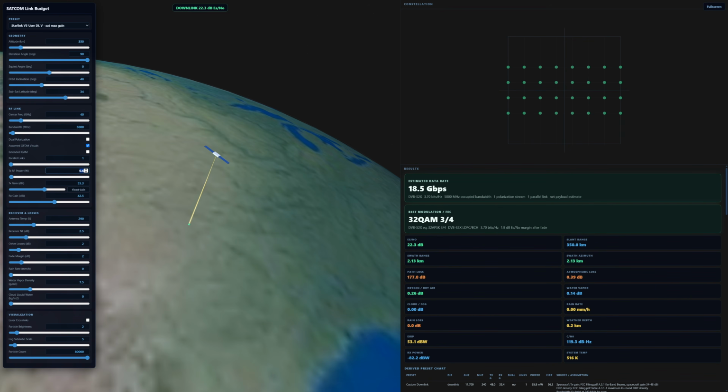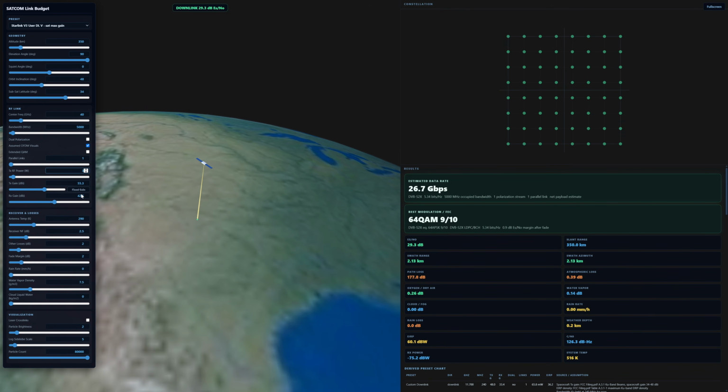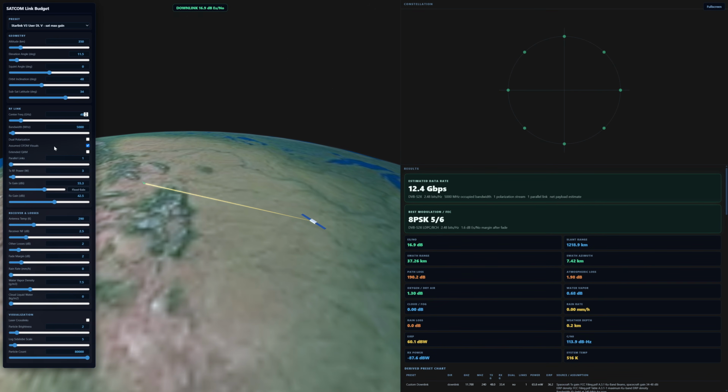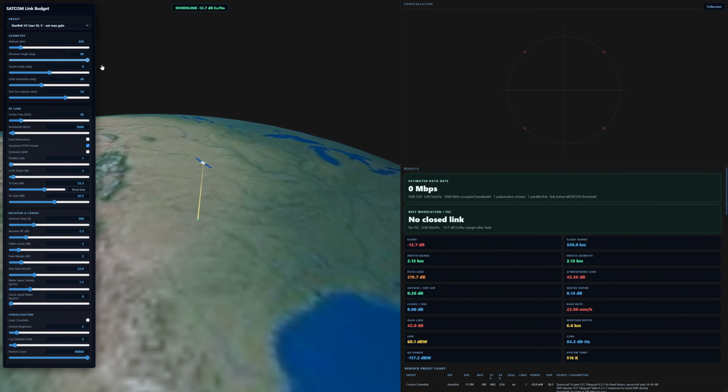When we compare to Starlink V3 V-band, we start with a much better link budget. At good elevation angles, we can use high code rate 64 QAM and still have higher data rates with single polarization out to 10 degrees elevation. It can handle somewhat heavy rain at ideal elevation angle, but in a severe storm, it would still get knocked out at full bandwidth and need to lower the data rate, or get knocked out completely.